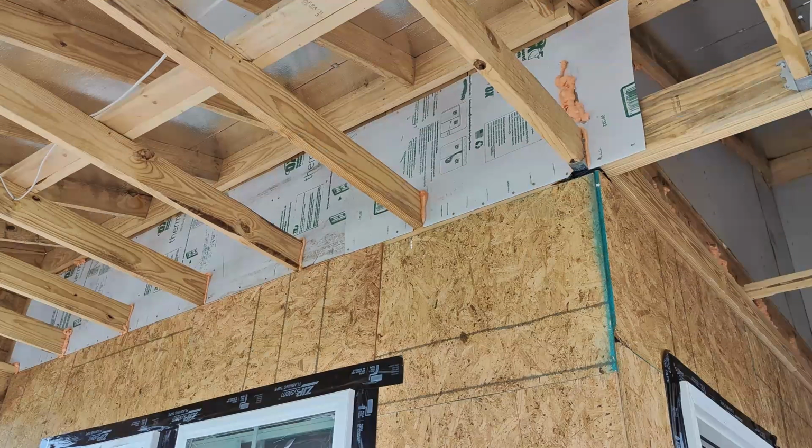Same for walls adjacent to porches and patios and the attics of those porches and patios. In the past, in these areas, the insulation was left exposed to uninsulated attics due to the exterior air barrier not being installed. So code now specifically requires it. Not having these, again, you'll hear me say the term over and over again. It's a misalignment of the thermal envelope, either with the air barrier or with the insulation thermal boundary. They must be continuous. They must be aligned.